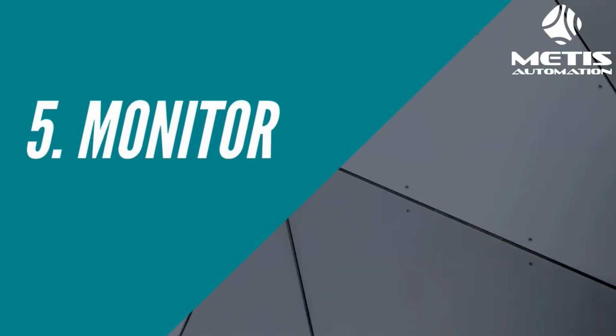So taking measurements is key to understand how well you're doing. And then number 5 is to monitor it. So you may have lots of detailed measurements, but identify a few high-level KPIs that will help you identify key trends in your manufacturing process that will tell you whether you're on track to having low variation. And that might be the results of the functional tests at the end of your production line. It might be a key measurement of the materials coming in, but just identify 2 or 3 of those which you think have the biggest impact, track those over time, and that will tell you whatever things that you implement, if they're on track to making the improvements.